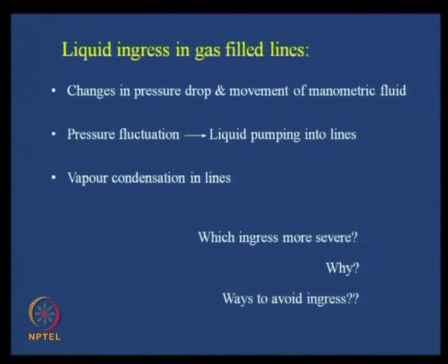But the good part is, see, in the manometer the movement of the liquid is much more vigorous. Okay. So, therefore, this pumping action is much more there. Here the diaphragm moves to a very small extent. So, therefore, pumping action is not so very high, and therefore, the ingressing of the second fluid into the manometer line is not so very serious also. Okay. But for differential pressure, we usually always use liquid filled lines, just in order to minimize the pressure fluctuation part.